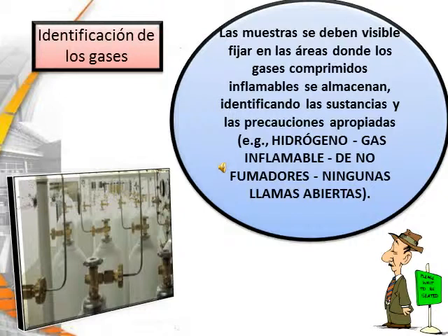Signs should be conspicuously posted in areas where flammable gases are stored, identifying the substances and appropriate precautions. An example of this would be hydrogen, flammable gas, no smoking, no open flames.